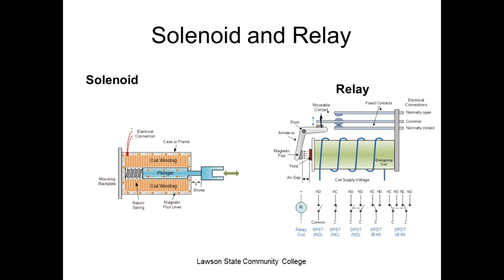Oh yeah, you got all kinds of relays. You got a bunch of relays in your car. Usually they're outside under your hood. That little click that you hear when you turn on your lights. Used to, you had a big old switch to turn on your lights, and we had the dimmer. We had a dang thing in the floor, which is a big old switch that you had to hit, because they were actually controlling the lights. Now, how do we dim our lights? We got something up here on our little steering column, right? But what you're doing is that little steering column is bringing in a relay, and the relay is controlling the lights.